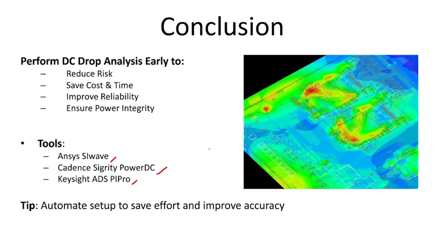So I have developed some automation scripts so that users don't have to spend this much time, and the automation will take care of running the simulations and giving a report on whether this voltage rail on this design has passed or failed. This report can be used between the layout engineers and simulation engineers, and accordingly they can improve the power distribution network quality.